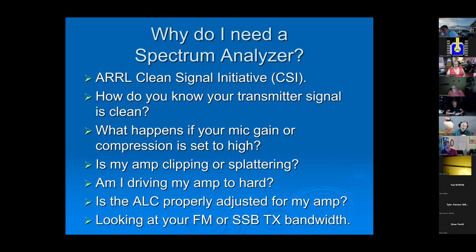On a tube amp, when you drive it too hard, your grid current is going to go up. When your grid current goes up, that's a very good possibility that you're going to start melting the plates in that tube. So having ALC set properly is going to save your amp, and this helps you understand your output power and know when that ALC kicks in to not let you push the power further and cause any damage to your tubes and amps.